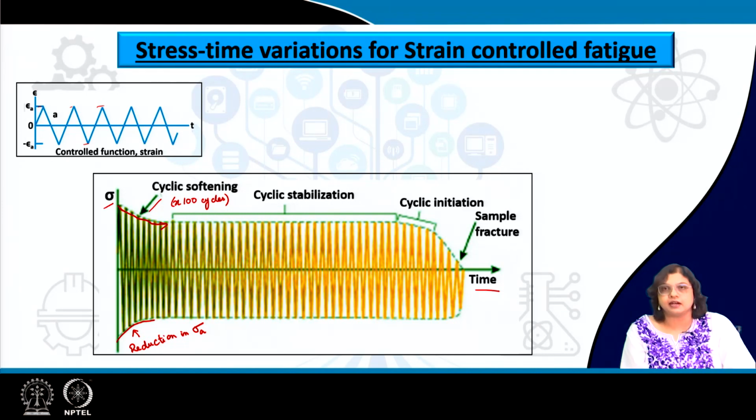If we are applying a certain value of strain, whether in elastic or plastic condition, it should have some particular value of stress amplitude. So, after some initial cycles of this discrepancy of hardening or softening under cyclic loading, we are seeing the major part under cyclic stabilization, when the corresponding stress output will have the same value at every cycle.